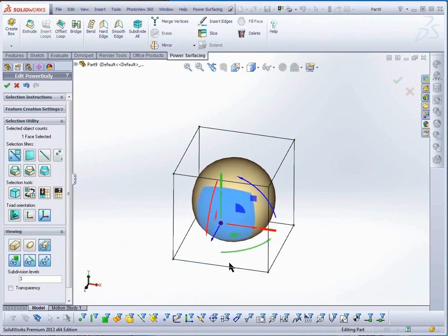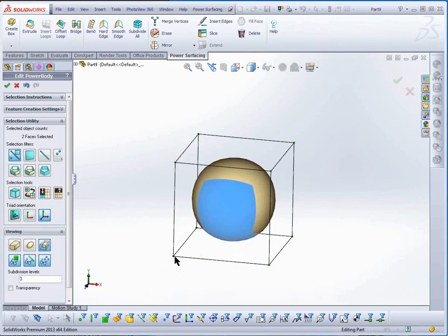You can hold the Control key down and continue picking, or Region Select to add to the selection. Region Select works the same as the rest of SOLIDWORKS. Dragging from left to right selects Windowed, while dragging from right to left selects Crossing. Note that as soon as you select an element and hold down the Control key, you will only be able to select more of the same type. To remove from the selection, hold the Shift key and pick or region select. Releasing the Shift or Control keys returns to the Select Any mode.